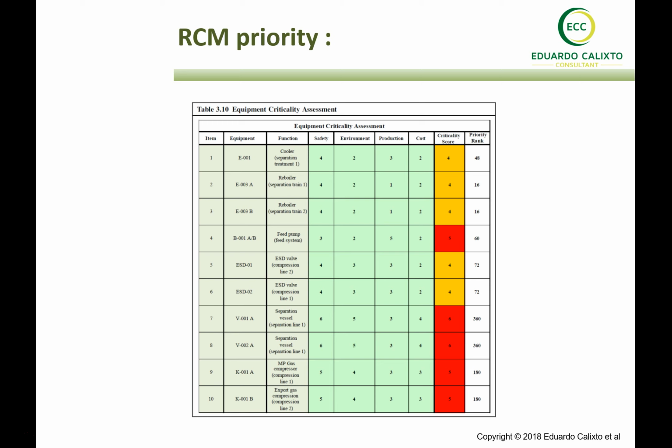But even though we need to prioritize, when you look at equipment, a pump is not a big issue, but a compressor, for example, or a turbine, has a lot of components and subsystems surrounding it. So we need as well to prioritize the components that will be assessed during the RCM in order to get improvement along the RCM implementation. Okay, so this criteria is very important to define which one we start with in our RCM concerning a plant's process.